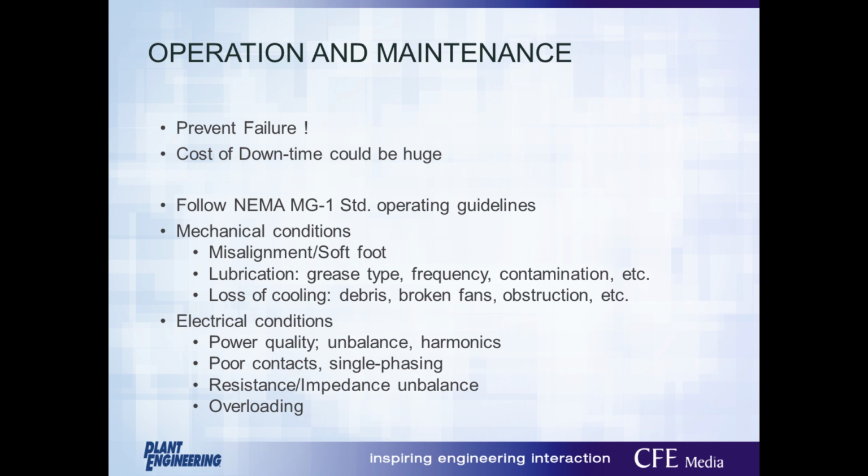If the motor is hot and you want to compare winding resistance to the original manufacturer values, then you'll need to let the motor cool down for quite a bit to have an apples-to-apples comparison. If the resistances are out of balance, then you may want to run some dielectric tests with a Megger or something similar. And of course, with all of this, only properly trained personnel should be completing the maintenance procedures and using any of the equipment that I've mentioned.